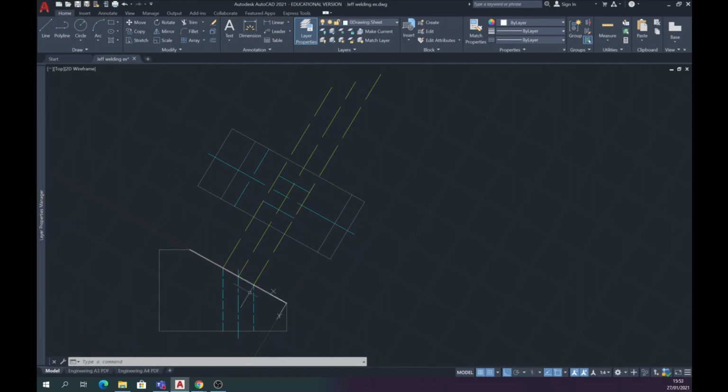So in order to get this feature here placed onto the auxiliary view, I'm going to use the ellipse command. But I'm going to pull the drop down and I'm going to use an axis end ellipse. So they are axised from the center line. So I'm going to click on that intersection, click on the second intersection, and then move down here to get one of these perpendicular marks that give me the end limit. I'm just going to place it.